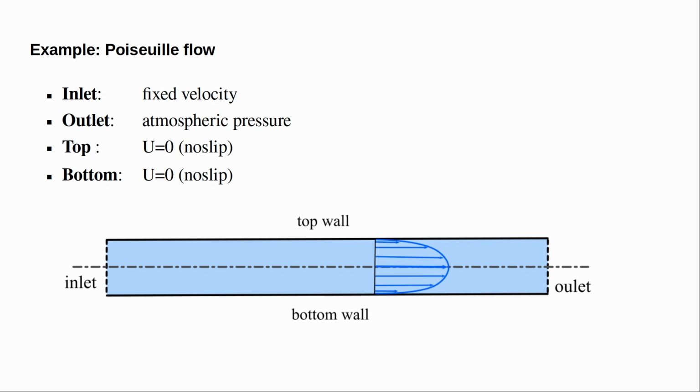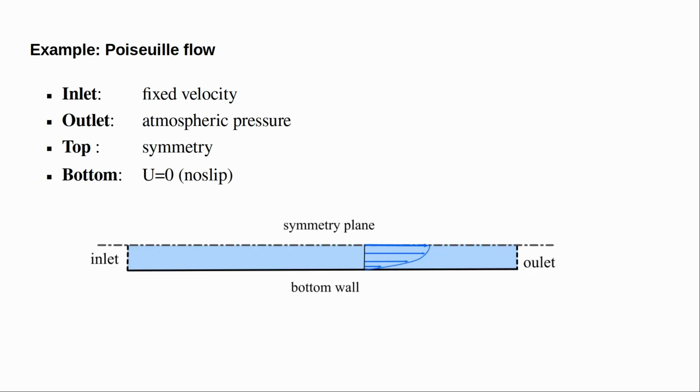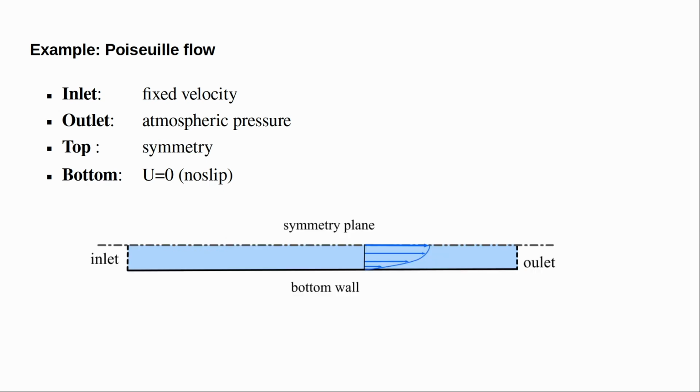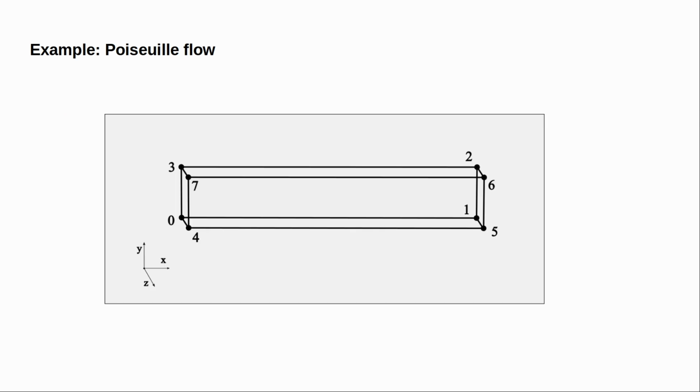Okay, as the flow is symmetrical, we can benefit from this to decrease the computational time by solving just half of the domain as you see here. So instead of solving the whole domain, I solve for the lower part only. And this is how the blockMesh code sees your domain. As you see, I added just one cell in the Z direction as OpenFOAM deals with only 3D meshes.